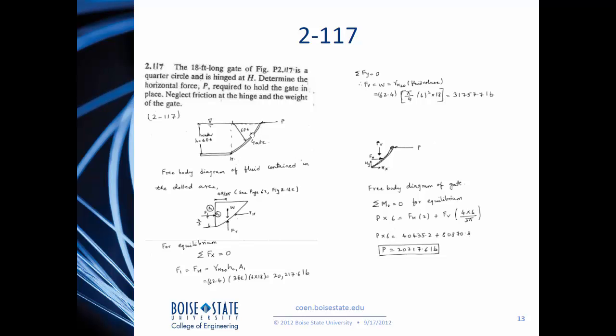So in this problem, we could treat this as if we were dealing with two planar surfaces. The way you do that is take a section of the fluid from the container such that we have two planar surfaces, and the resultant hydrostatic forces can be written as Fv and Fh, the horizontal and vertical components.